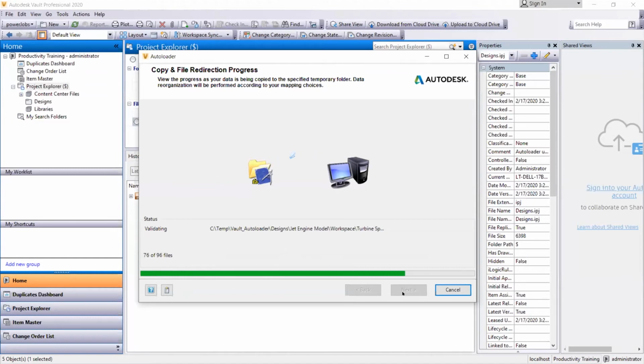And again, these are sample assemblies that I got from Autodesk, so they're pretty small. Your assemblies might be a little larger than that, somewhere in the thousands probably. We've seen some of our customers have assemblies that large, which will be fine to upload into Inventor. Once we get into the 10,000s or anything higher than that, that's when we would maybe think about breaking it down and doing smaller batches, or even using a different method. Once it's that large, if we want to break it up into chunks, we might end up using the task scheduler, which we'll look at in a little bit.